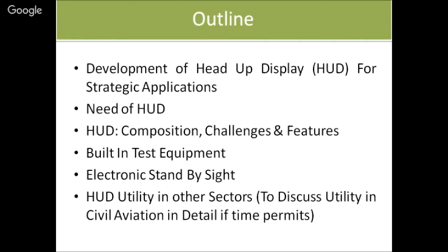Now, if there are around 250 devices in a cockpit, your device should be compatible to the total permissible EMI generated by all those 250. Plus, the EMI which is generated by your device should be less than the amount fixed for an individual unit.